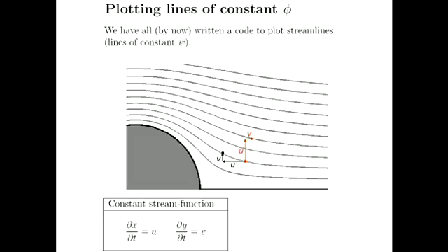So if we want to track a line that's orthogonal to that stream function, rather than moving u multiplied by time in the x direction, we need to move minus v multiplied by time in the x direction and u multiplied by time in the y direction. Does that make sense? Maybe what I'm saying doesn't make sense, but the figure makes sense, right?